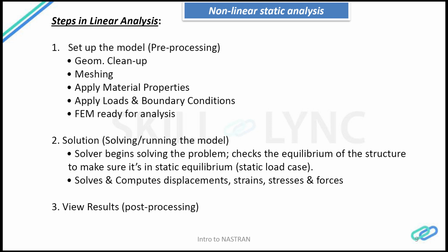Since it's a static load case, it makes sure that static equilibrium within the structure is established, and then based on that it applies the loading, solves the problem and computes the displacement, strain, stresses and forces and free body loads or whatever the user might have requested. And finally the user can view the results or check the results against his rough calculations during the post processing stage. These are the typical steps involved in the linear static analysis.